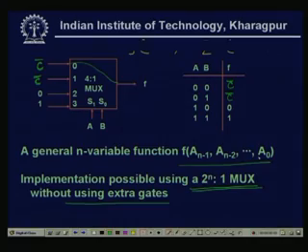Now, in this current example, we can even reduce the control signals. What we have done is that for n variables we have taken n minus 1 select lines, and the primary input is replaced by 0, 1, and the complemented or uncomplemented input which is left.